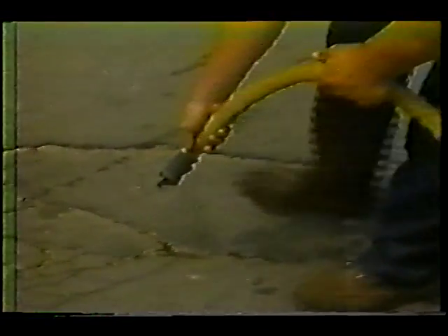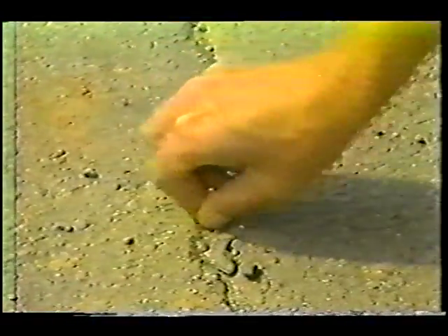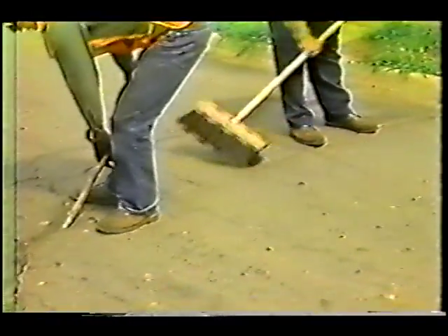After the pavement surface area and cracks have been cleaned, you must inspect them for damage. Identify the cracks that need more cleaning to your crew. A sharp-pointed rod may be necessary to remove any material stuck in the cracks. Remove any loose material from the area to be repaired.